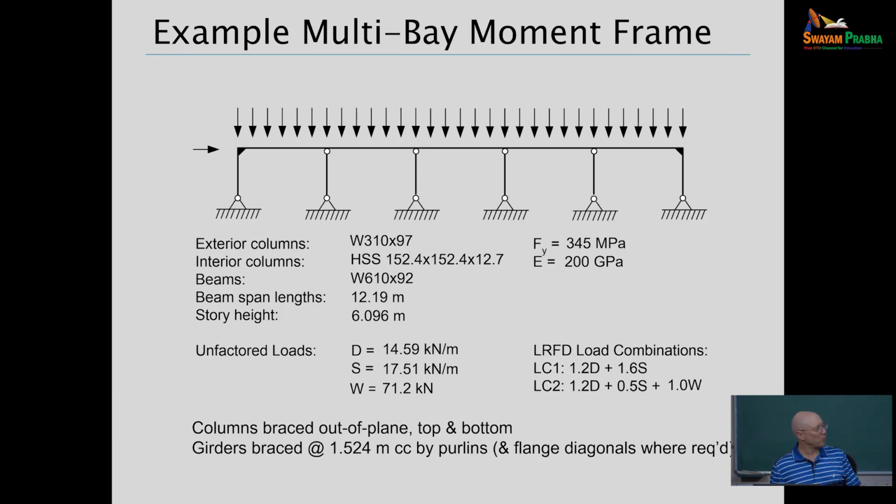In terms of the lateral load resisting system, it's the exterior columns. The little triangles there mean it's a rigid connection of the roof girders to the columns there on the end. And so the member sizes that you see here, yield strength of the steel is 345 megapascals.